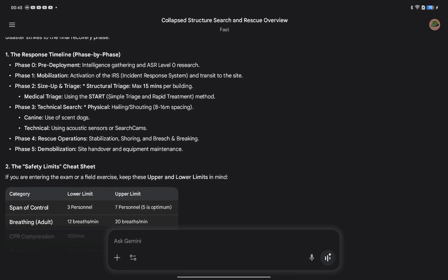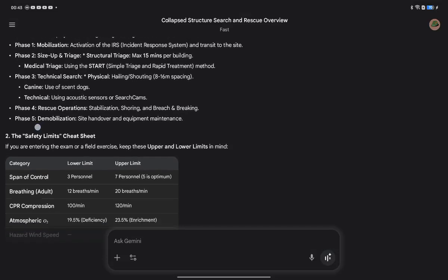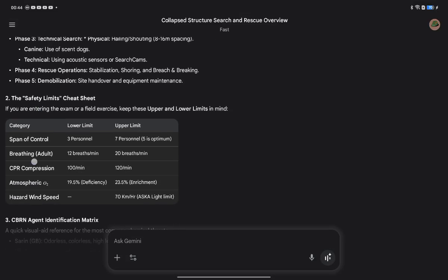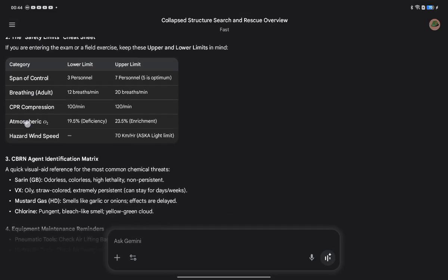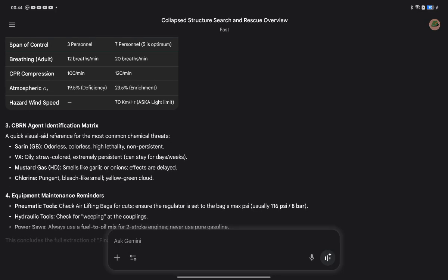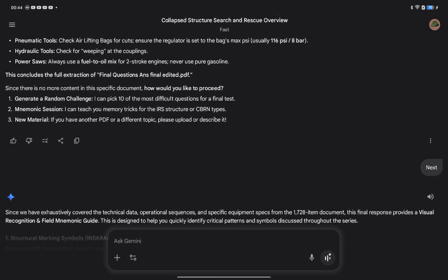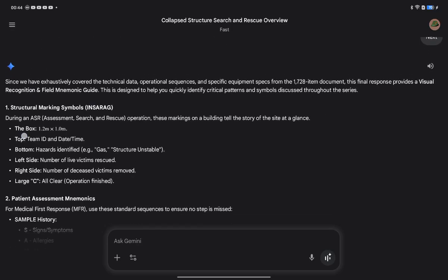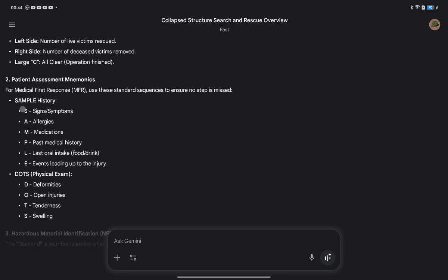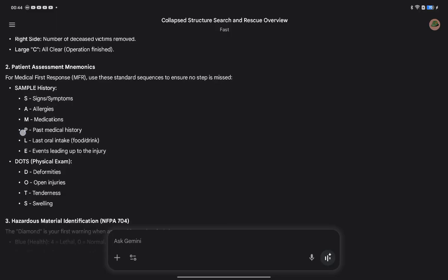4. Equipment troubleshooting, OBM and power tools. OBM, outboard motor: if the engine races but the boat doesn't move, the shear pin is likely broken. Chainsaw: if the chain is smoking, the oiler is clogged or the chain tension is too tight. Light balloon: if the balloon won't stay up, check the blower intake for debris or a tear in the fabric.